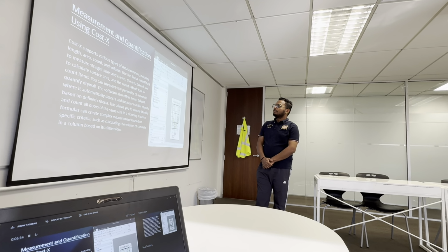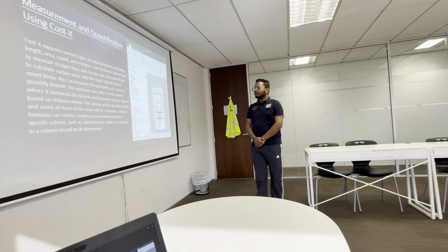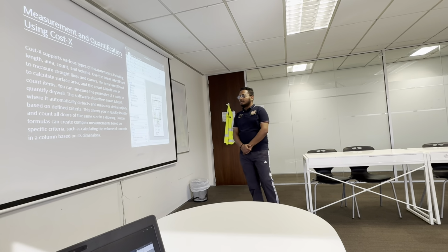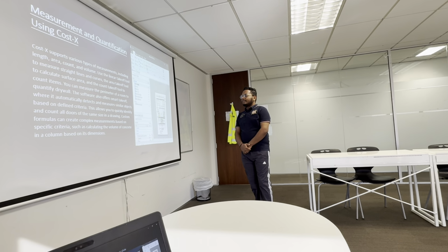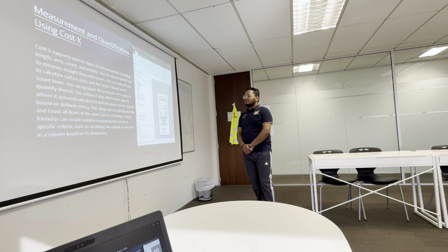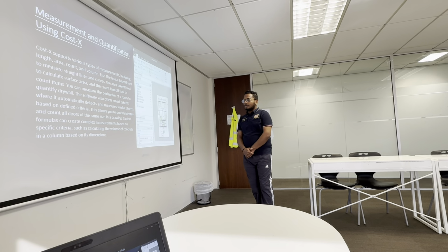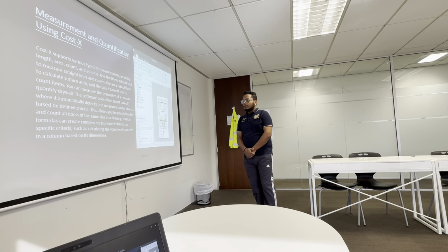The software also offers smart takeoffs, where it automatically detects and measures similar objects based on defined criteria. This allows you to quickly identify and count all doors of the same size in the drawing. Custom formulas can create complex measurements based on specific criteria, such as calculating the volume of concrete in a column based on its dimensions. So next one.